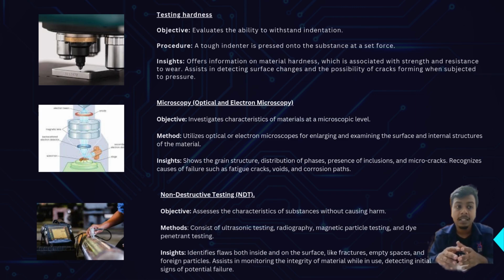The last one is NDT, also called non-destructive testing. It assesses the characteristics of a substance without causing any harm. It consists of ultrasonic testing, radiography, magnetic particle testing, and dye penetrant testing.